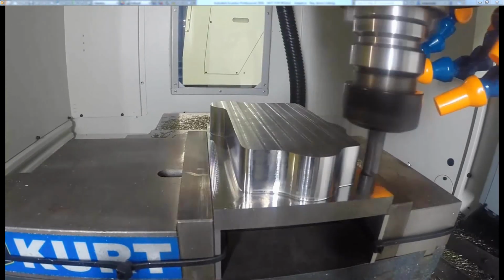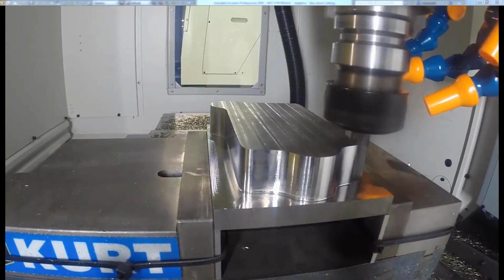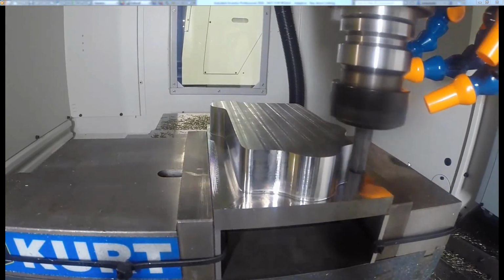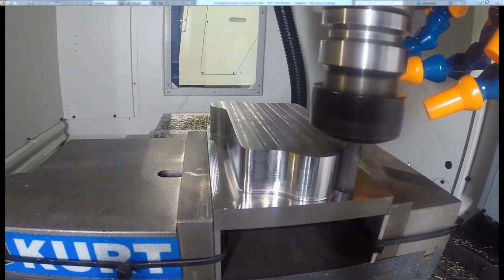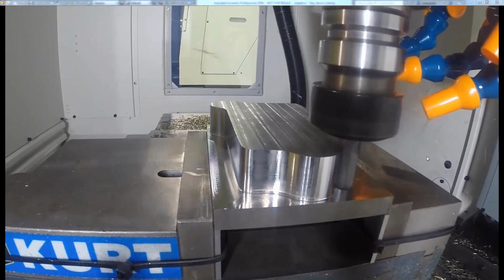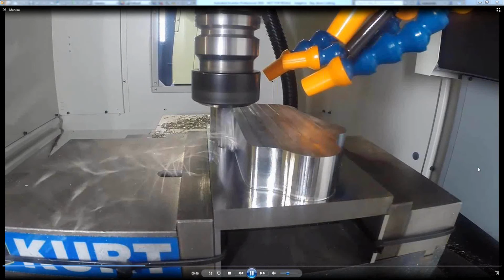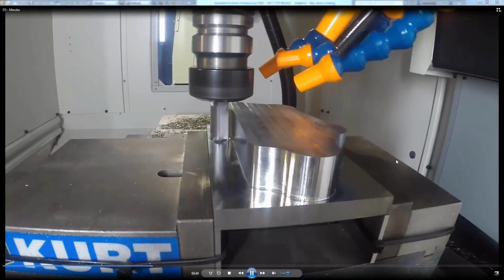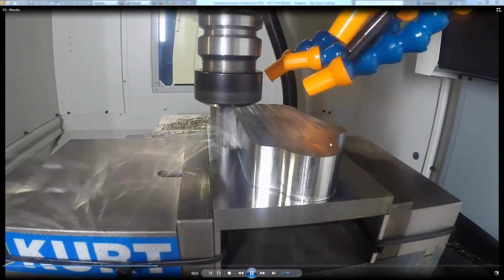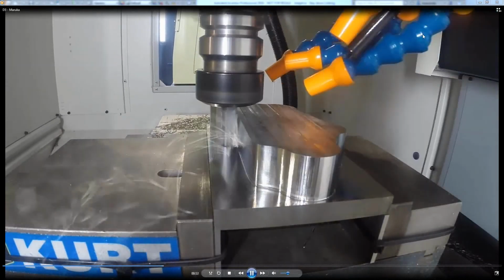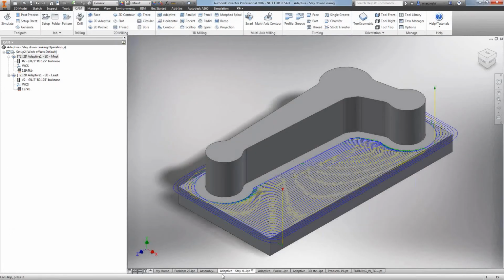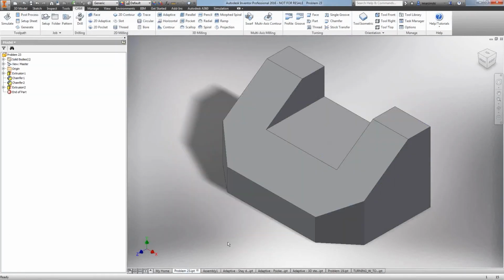So here you can see it just lifts up. I've got it set to, I think, 10 thousandths. It's coming back around and making those movements. So maximum depth of cut, shallow passes, really reducing machining time and maximizing our tool life. Okay, so back to our problem now.